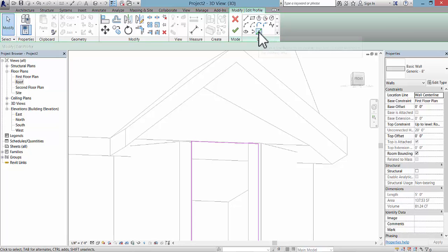And then here I'm going to click on pick lines. When I click on pick lines in the draw panel there, I can click on these two roofs and create this triangle. So here I can use this trim extend to select this purple line and this one. See how it's kind of coming out this way.